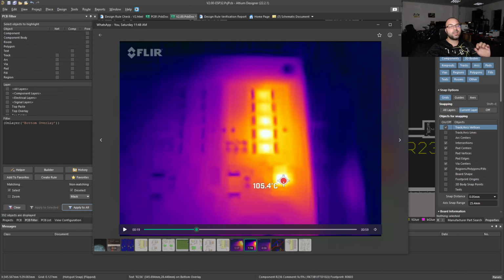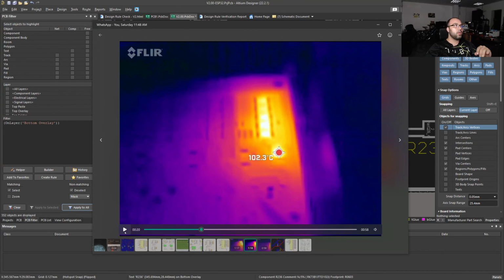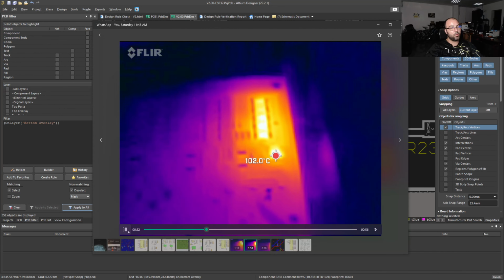But this MOSFET is good till 150 degrees, and that will keep it in the working conditions tested in the datasheet, because they test it up to 150 degrees, but it's more likely to burn when it gets to 190, 200 degrees. But with improved airflow from the lid, it should stay within the range.